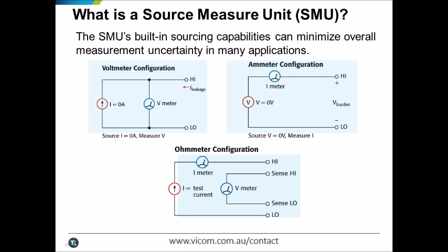For current measurements, the SMU's built-in source and feedback ammeter design work together to keep voltage burden low and enable low current measurement to sub-picoamp levels. DMMs do not have the built-in source and typically have shunt ammeter designs that limit low current capabilities to nanoamp levels. Finally, for resistance measurements, the SMU architecture offers full flexibility over the amount of current or voltage being sourced into the device under test. DMMs have fixed current source values that are dependent on the range being used to measure resistance.